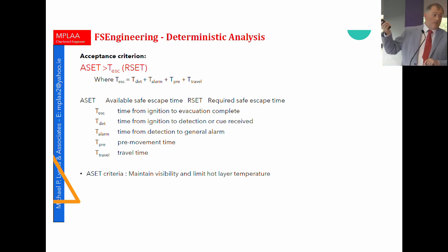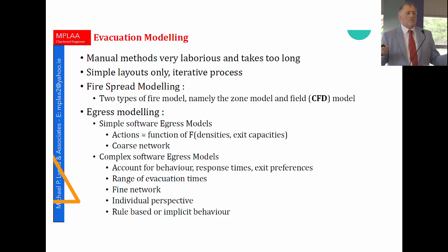You can model all of this, of course. You take the architectural configuration of the building, create a computer model of the building, put it into a software package that figures out how long it's going to take for everybody to evacuate in all the different configurations. There's the egress modeling. It can be a very simple model based on just simple actions by people and the density of the people within a particular room to evacuate that room.